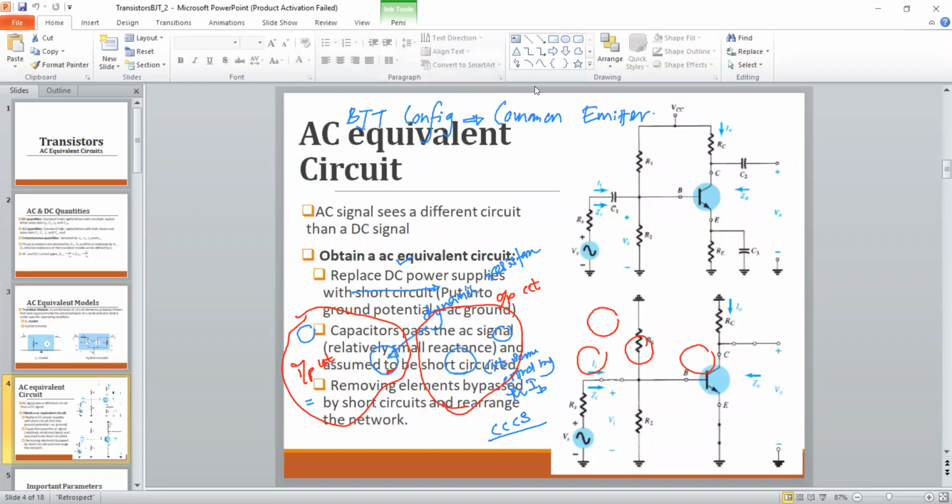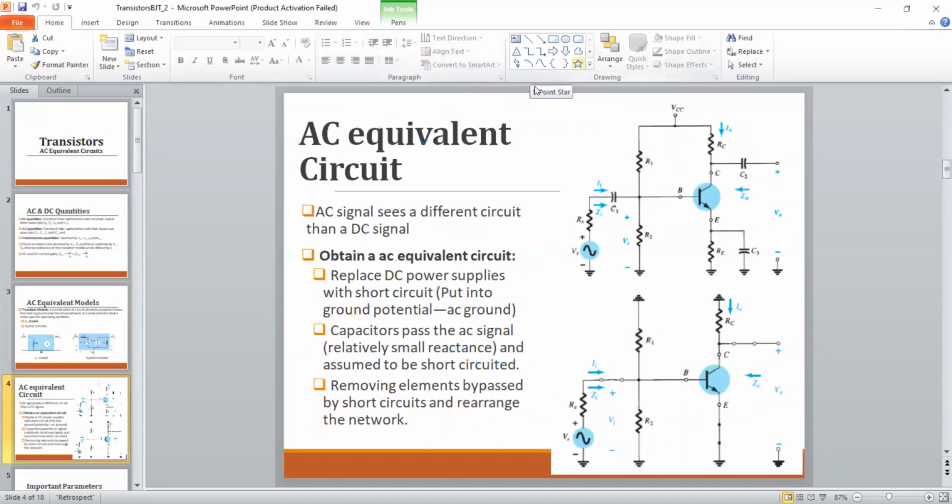Now, if you are given a transistor circuit, if we are dealing with DC quantities, we should simplify the circuit to the DC equivalent model. In that case, we simply replace the capacitors and inductors with open circuit and short circuit elements respectively. With that simplification, you can convert the real transistor circuit configuration to the DC equivalent model. Only then can you apply Kirchhoff's voltage or current laws in the DC domain.